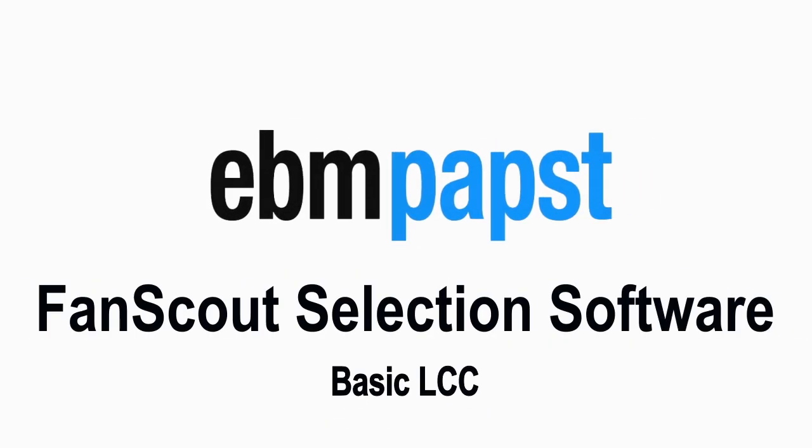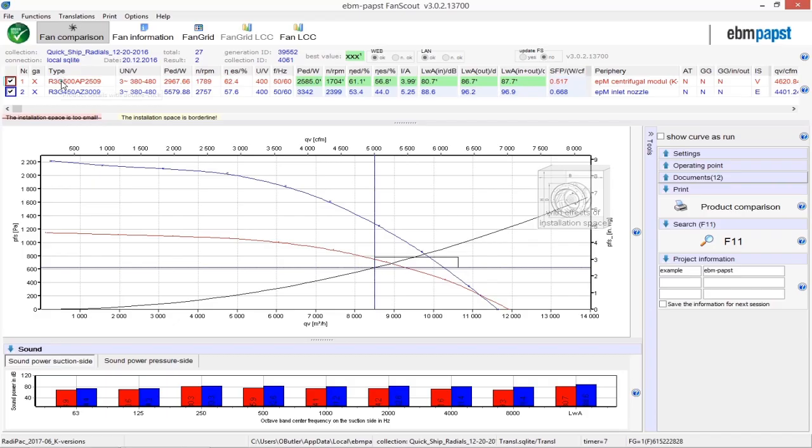Welcome back to the third installment of the ebm-papst RPM FanScout tutorial, where we are choosing a fan based on the calculations of its lifetime costs. To begin your life cycle cost analysis, right-click each fan and select Add Fan to LCC. Now head over to the Fan LCC tab.